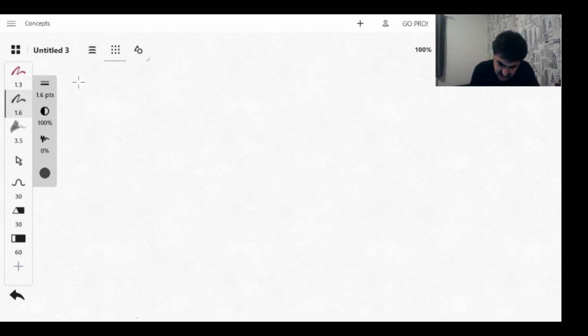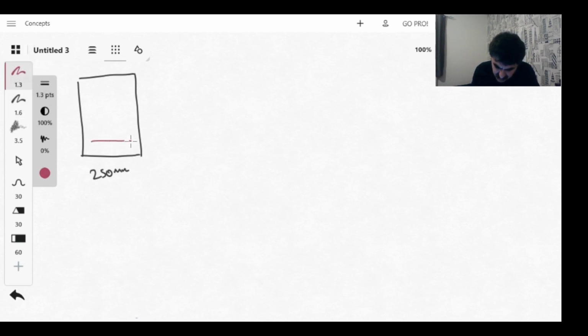So I have a section like this, a beam section, and the width of the section is 250 millimeter, and I have steel reinforcement. I don't know, it will be 1 or 2. I will have it in the negative region as well, but here I have it. This should be 50 millimeter according to the equations. And the other D, you remember D is 500 millimeters. So actually total height will be 550 millimeters.